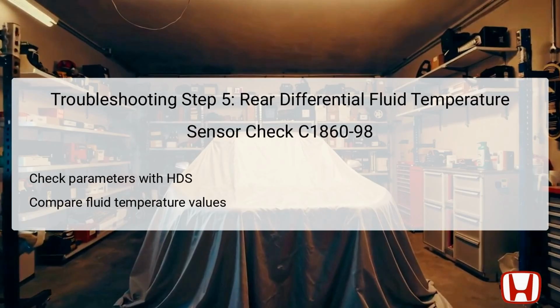In this step, the technician utilizes the Honda Diagnostic System, HDS, to examine the rear differential fluid temperature sensor's readings. Checking parameters, such as the current oil temperature of the differential, is essential to ensure that it operates within acceptable ranges. After determining the temperature, comparisons are made with the expected standard values for proper operation.